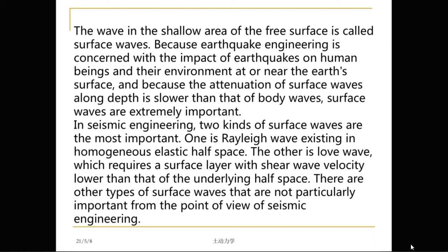Because earthquake engineering is concerned with the impact of earthquakes on human beings and their environment at or near the Earth's surface, and because the attenuation of surface waves along depth is slower than that of body waves, surface waves are extremely important. In seismic engineering, two kinds of surface waves are the most important.